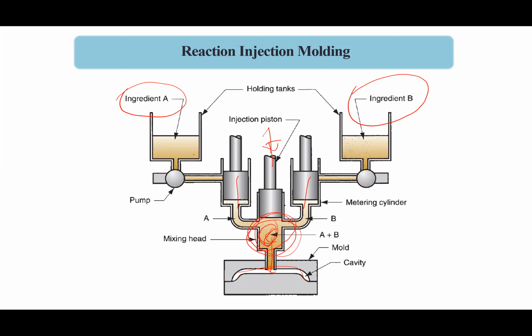This can also apply with the epoxy that I have told you. For some epoxy parts, you can produce them by mixing resin and hardener, putting it into the mold, and then you remove that mold, put another mold, and you take the material and keep it in another place. It requires 24 hours for curing. Then you keep that mold in another place for 24 hours, and after 24 hours you take that material out.